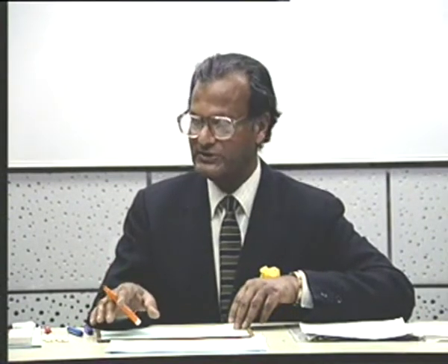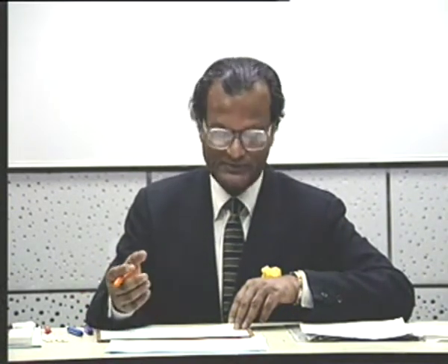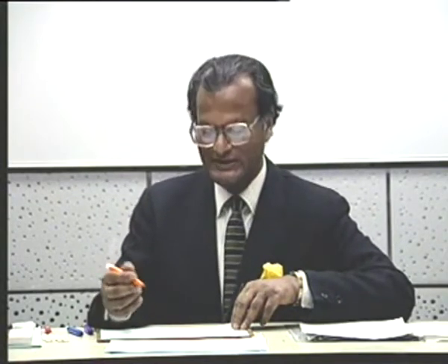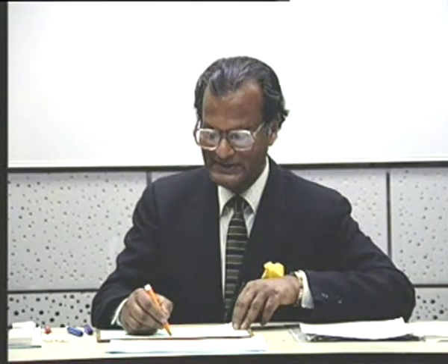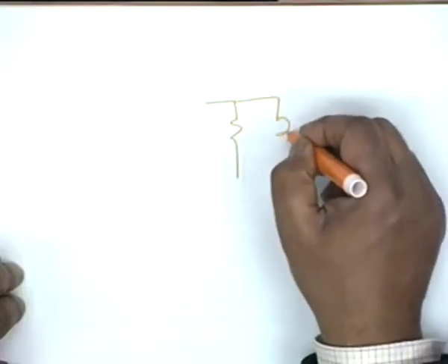So series and parallel resonance are very similar phenomena, and one should not be surprised to see the similarities, because one circuit is the dual of the other circuit. The role of series connection is taken over by parallel connection, the role of voltage is taken over by current, and the role of current is taken over by voltage. However, there is an important distinction now, namely that if you have, let us say, this parallel resonance circuit,